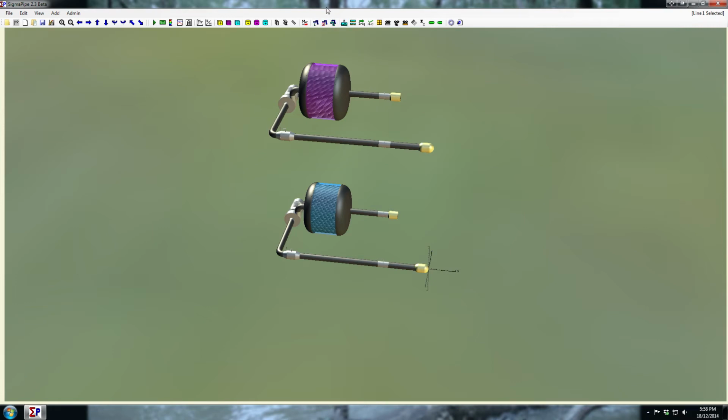This is your add, or your editing your piping network. So you can copy lines, you can add new lines to it. Here we've got 2 so far, and you can also edit an existing line. So if you need to, oh sorry, I forgot, this is supposed to be a valve instead of an orifice. You can go and you can change that.